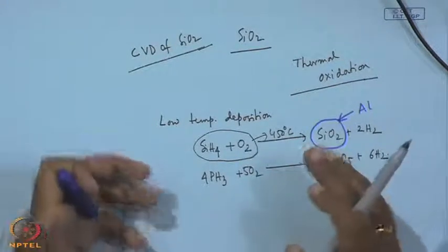In semiconductor processing, we often see that different kinds of layers can be grown on different types of materials. In this particular example, we can grow SiO2 over aluminum, that is, the metal layer, and in this case the temperature is the driving force because of the melting point of aluminum, which we just discussed. Then in the intermediate temperature range, we can use TEOS.